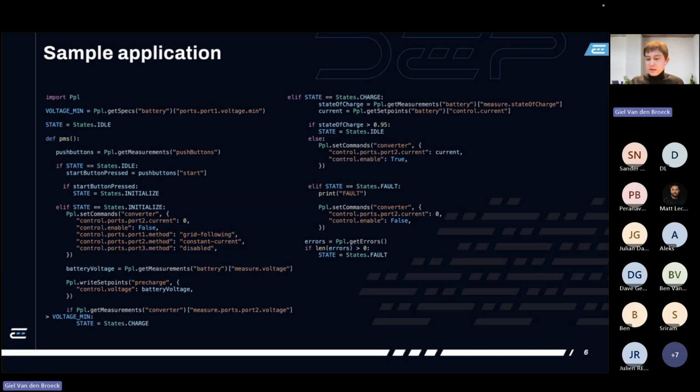We're not going to use it now. This could equally be constant voltage, 350 volts for instance, to energize a DC bus. But in this example, it's just a grid-connected battery, grid following on one end, and it will provide whatever power is needed to compensate for how much power we send to the battery and the internal losses of the converter. Then we can measure the battery voltage, again, one single line of code. And here we get 400 volts, for instance.